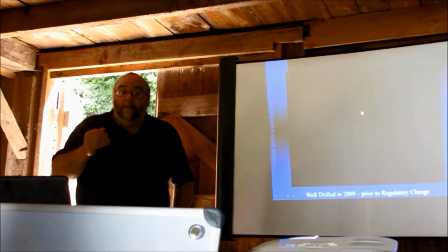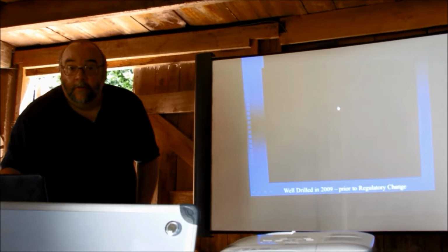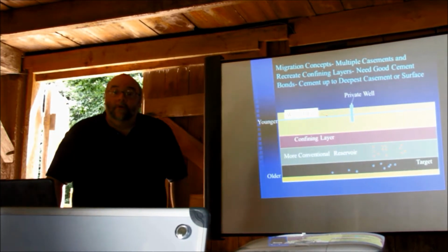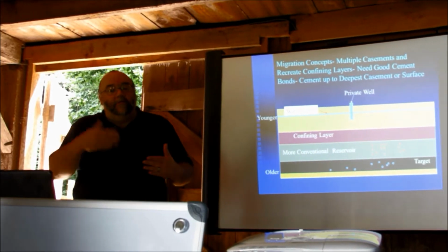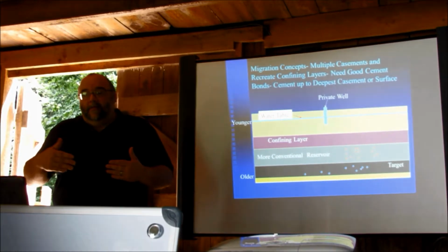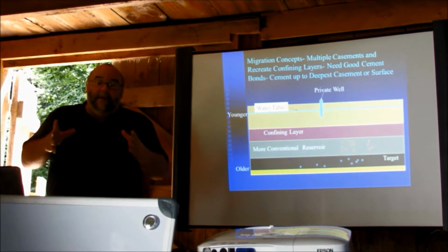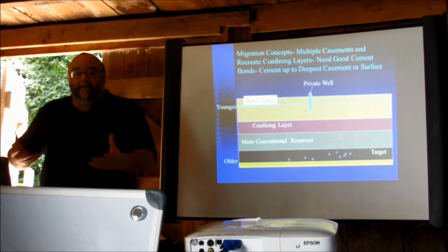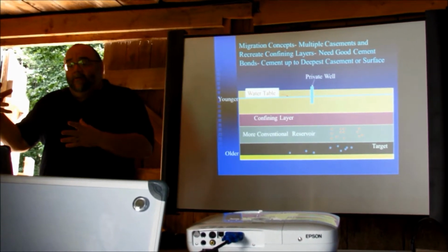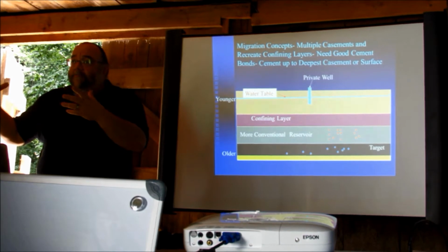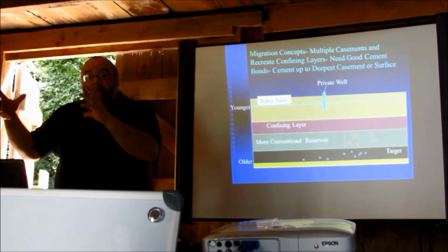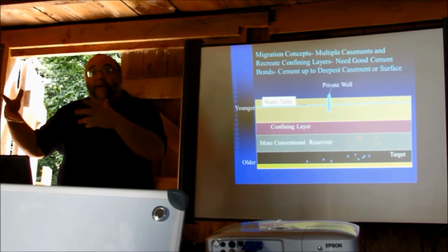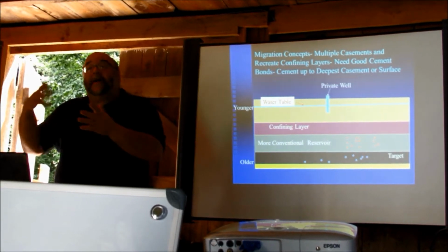Yeah. And what about if there's methane migrating? What else can migrate with the methane into the surrounding area? Yeah, usually when you have methane migration, it's kind of hard to move fluid with it, but what can actually happen is the methane can migrate from, let's say, the deeper aquifer into the shallow aquifer, and the methane can actually create a reduced zone in the aquifer. And when that happens, iron and manganese and other metals can get dissolved in the water, and that could also show up in the well.